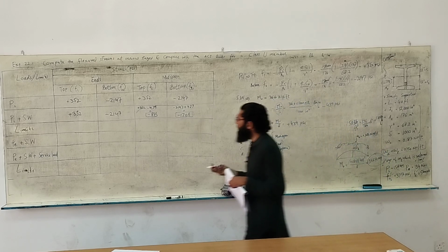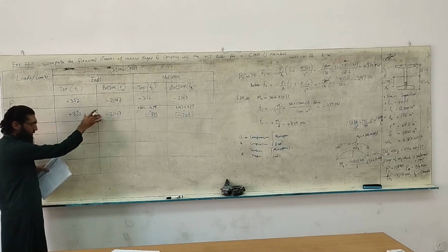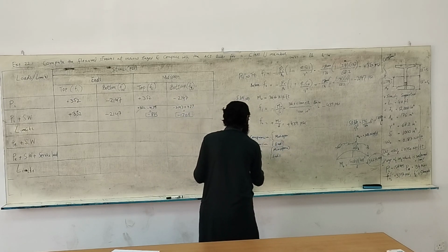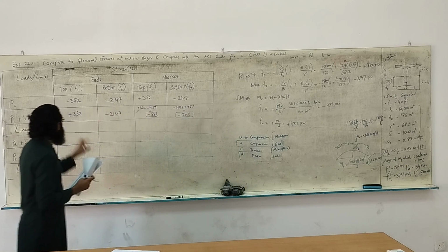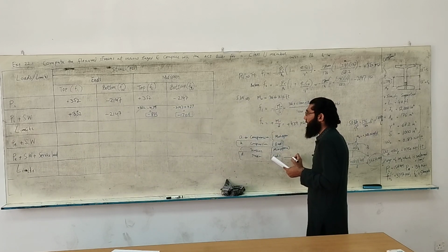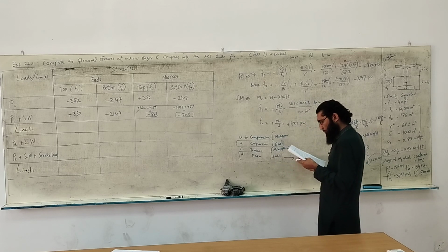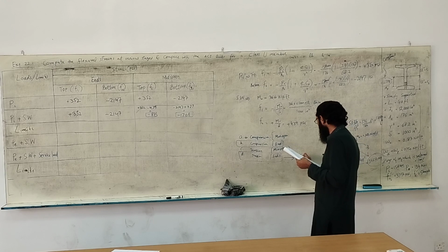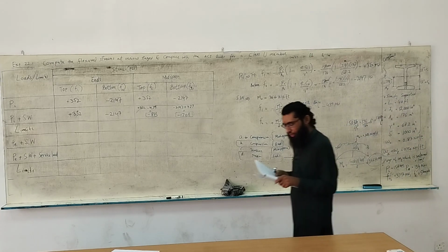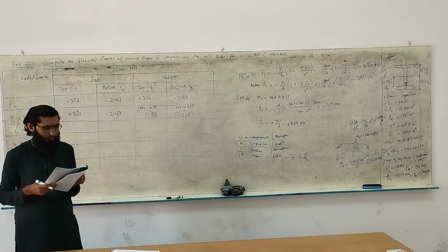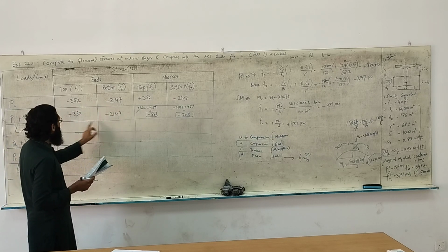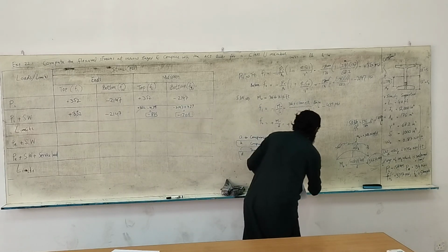So let's first do maybe the ends. Let's write down the limits for the ends. We would look at this one and this one. Now at the ends, what are these limits? Let's go to the tension first. This one says the limit is 6 under root of f'ci. This is the extreme fiber stress in tension immediately after transfer at the ends of simply supported members. So the extreme tensile stress that is allowed is given by this. Can you just calculate this number?